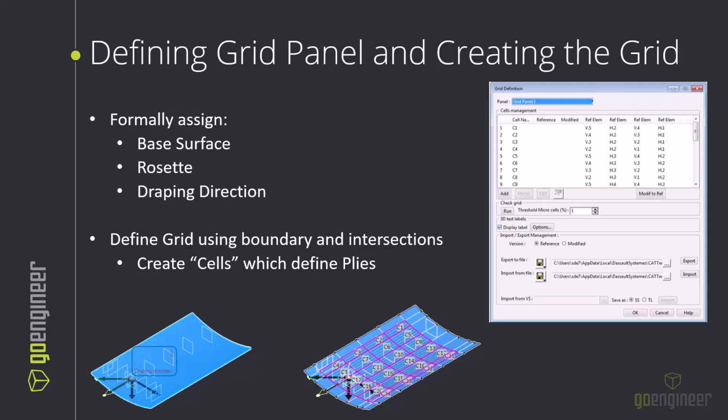So the process of having a stack up of materials in a single cell is known as a laminate. So in those composite parameters I mentioned earlier, in laminates, we can define a single pattern of stacking of materials or sheets of plies for a single cell. So instead of defining each cell layer by layer, we can just give it a laminate from those composite parameters.